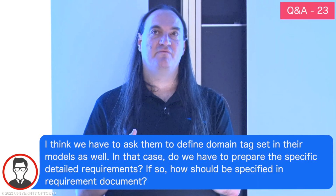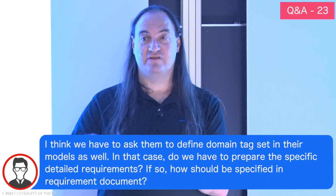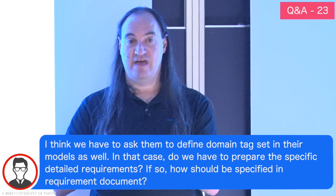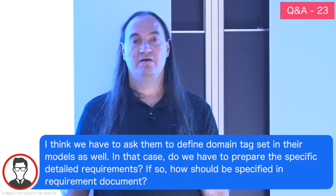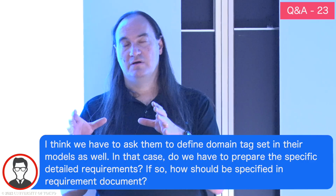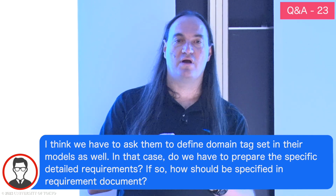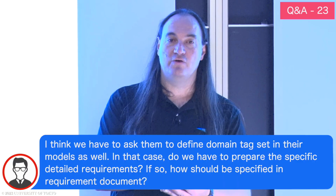And it will figure out, when it makes the contact or does the calculations, what surfaces are defined in the domain tag set then. So it's almost a container for you entering something later, a node, a set of surfaces, and so forth. It can be used just as groups. It can be used for establishing contact between objects. It can be used for applying a heat load to something.